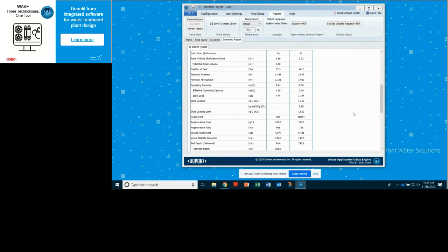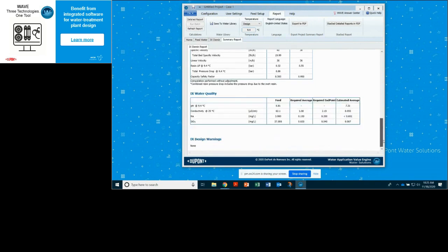Yes. Correct, Donna. And like I said, the best way to verify it is simply watch your pH. If your pH gets much above 7, you've over-degasified. Mm-hmm. And I don't know if you would pick that up, right, Garth, if you don't have that degas screen open that shows you those values, and so that's a good thing to have. And yes, keep an eye on the pH, like Garth said. Thank you. Yes, Garth, we had one person that over-degasified, and they had a pH of 10 here. They're wondering, how did they get a feed water pH of 10? And that's where we got into this whole discussion of the correct level of degasification.